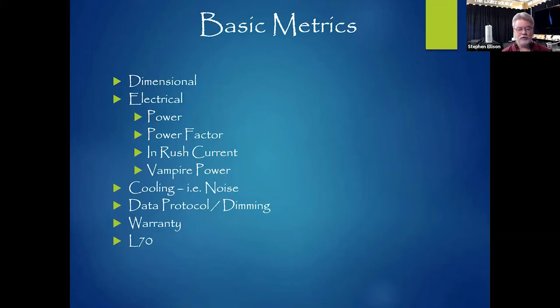But the inrush current can be a lot more and can affect that. If I have 8 fixtures at 100 watts, that's only 800 watts. That should be well below the rating of the breaker. But if their inrush current is equivalent to 500 watts each, now it makes a big difference. Now that might be milliseconds, and so you may be good, it may work, you may not have a problem, but you never can tell whether the inrush current is going to be more than the breaker can handle.